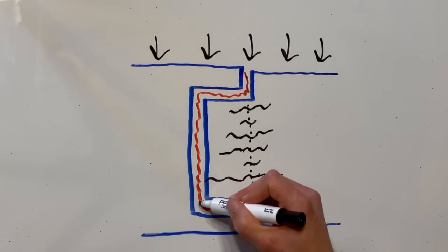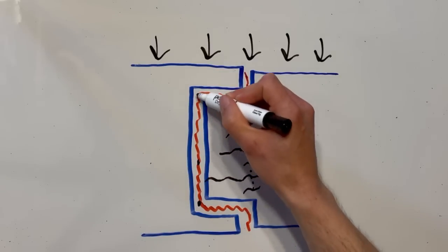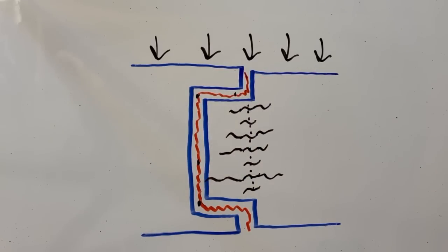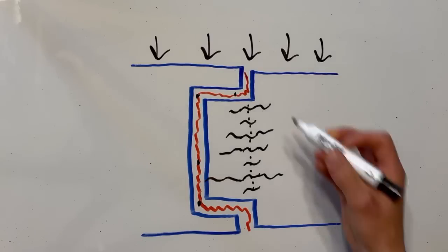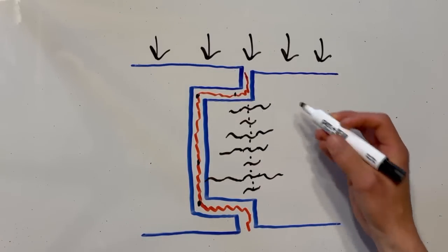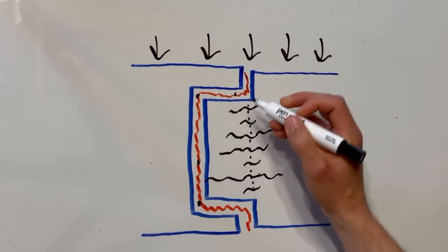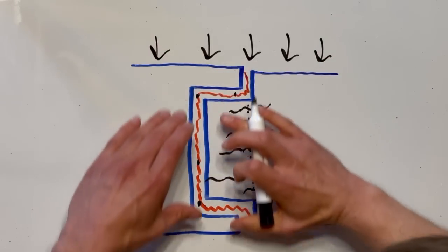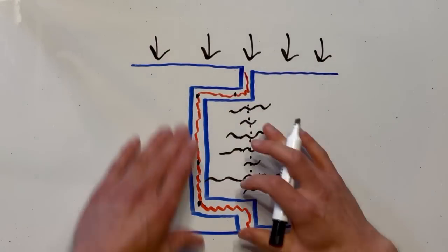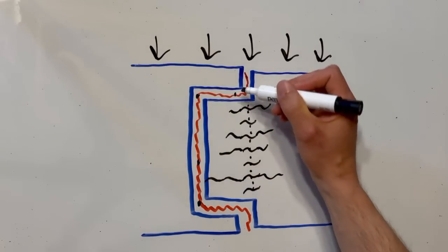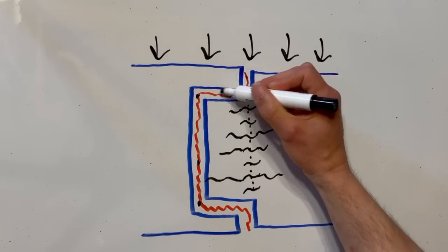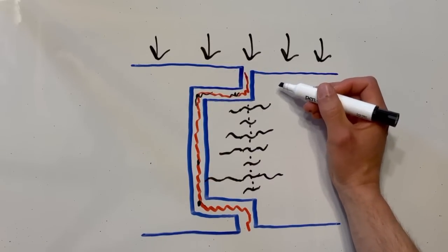Now there were likely lots of air inclusions in this adhesive. And possibly over time, some of those inclusions, also with the pressure cycling and possibly the shear stresses between the titanium and the composite, also might have opened up into cracks.